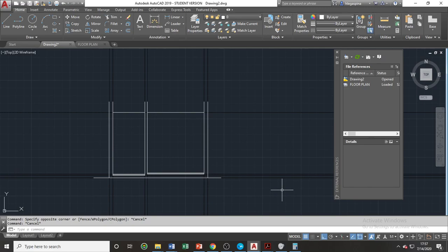The shortcut key for turning off layers is LAYOFF, or in the phonetic alphabet, Lima Alpha Yankee Oscar Foxtrot Foxtrot. So let's type LAYOFF and press spacebar. The usage of this command is just the same as your LAYFRZ command.